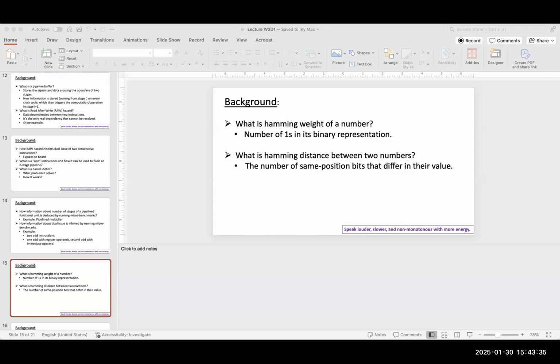The second part of the first question was how many ALUs are present. They answered that, and then asked whether all of them can compute all the operations. To answer that, they ran different benchmarks and found that the multiply instruction and the shift instruction cannot be issued in the same cycle with an ALU instruction. Which basically means that both of the ALUs can perform the multiply instructions.